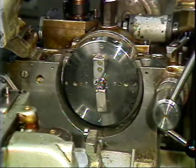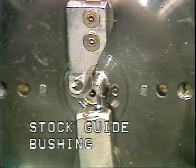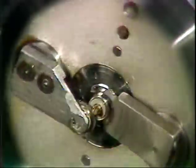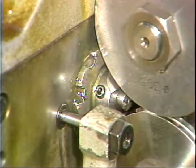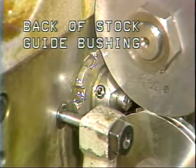Located in the center of the rotating tool head is the stock guide bushing. The purpose of the stock guide bushing is to support the stock during machining operations. The stock guide bushing is stationary while the tool head rotates around it. The stock guide bushing extends through the tool head and back to the stock feed rolls.